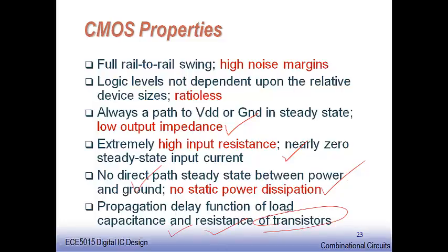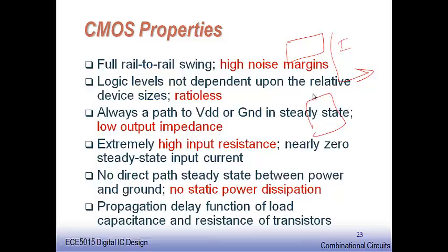I mean, why of the transistors? When the output node is getting charged, you have the PMOS pull-up devices conducting, that is sending your current. They make the current flow, and during the time of discharging, the current from the load discharges down. So at that point of time we will consider Rn, and during charging we consider the Rp resistances, and the CL, whatever be the load capacitances, they remain here.